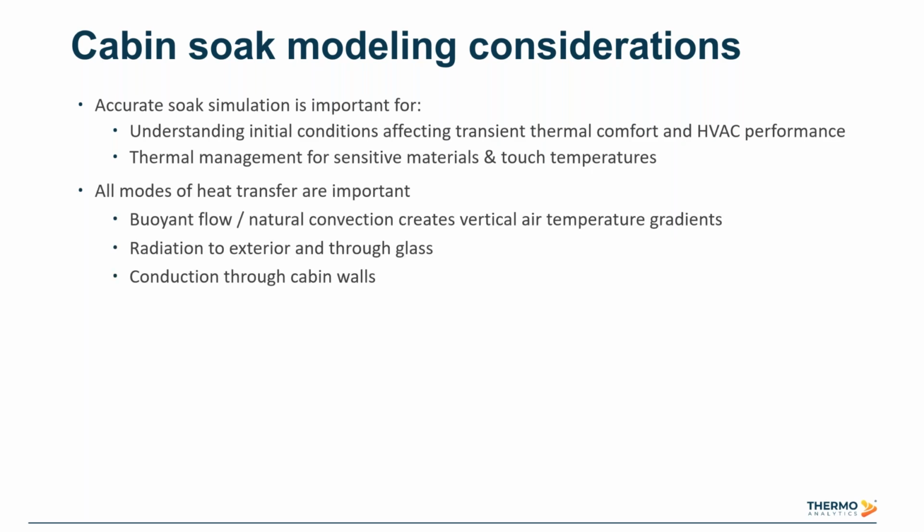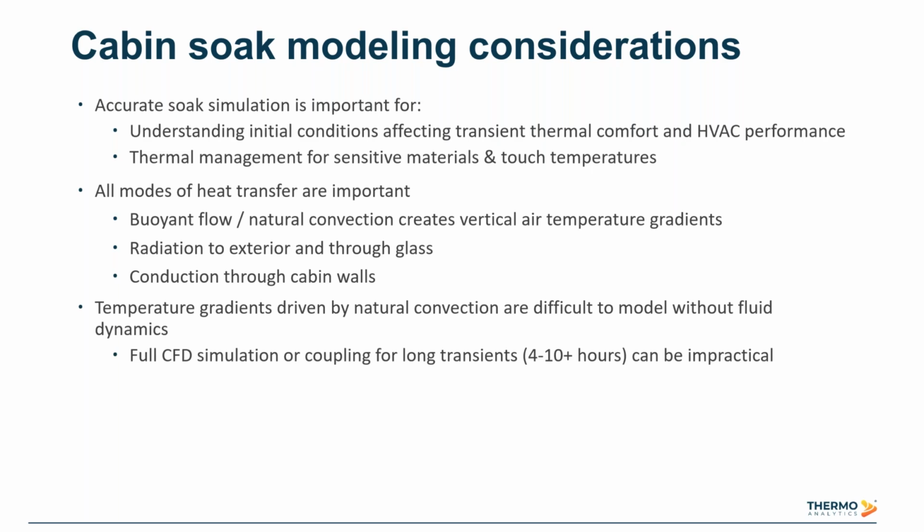Modeling soaks can be challenging because all of the modes of heat transfer are pretty important to get things right. Obviously, buoyant flow and natural convection creating vertical air temperature gradients. The radiation effects, both shortwave and longwave, through the glass and within the cabin, and those two working together to kind of create the greenhouse effect and temperature gradients. And we also need to understand the conduction through the cabin walls and the complex stack-ups that those sometimes consist of to understand how heat comes into and out of the cabin.